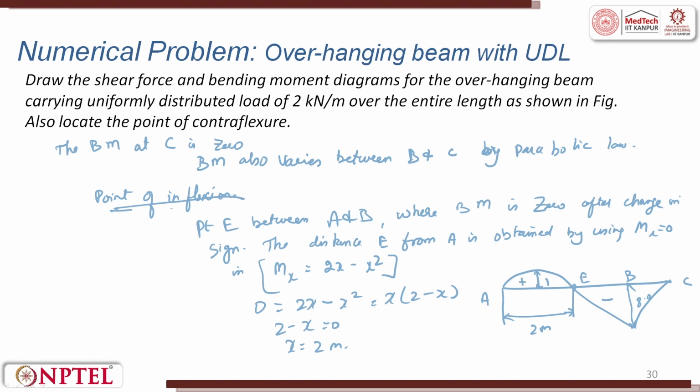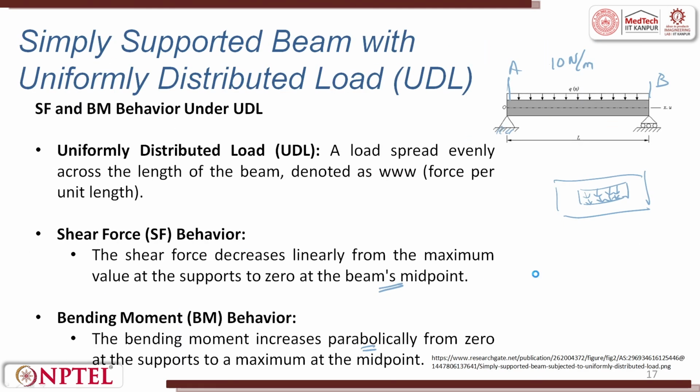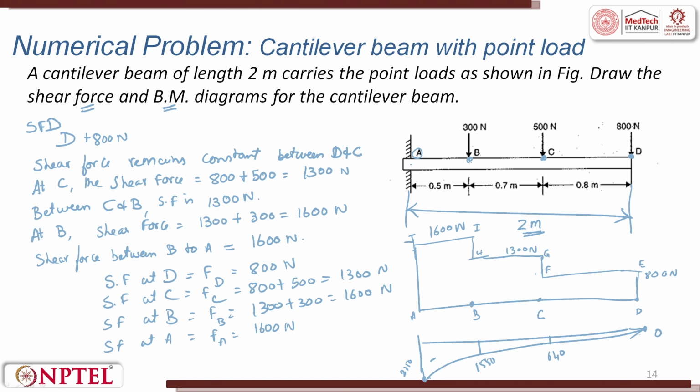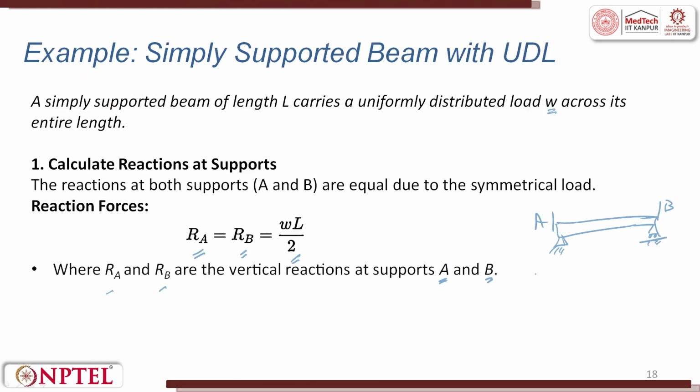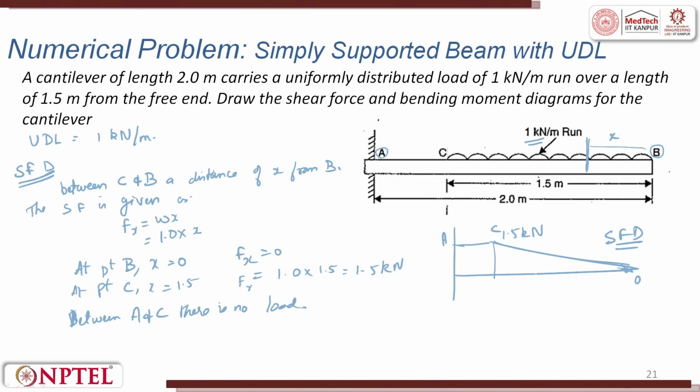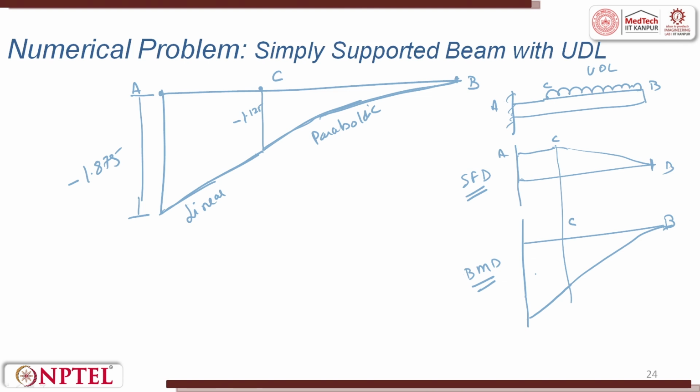Okay. So, we tried to solve 3 problems. All the 3 were pretty interesting. The first one we solved was a very simple problem, where we had a cantilever beam where concentrated loads are applied at A, B, C, D. So, we drew the shear force diagram and bending moment diagram. Next, we went to UDL applied to a cantilever beam. Here this is how the shear force diagram looks like, and this is how the bending moment looks like. You will have linear, then you will have parabola in the bending moment.